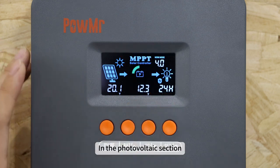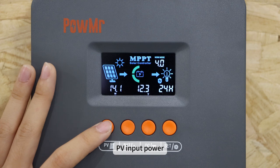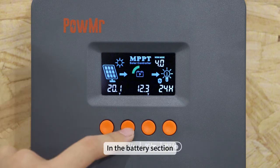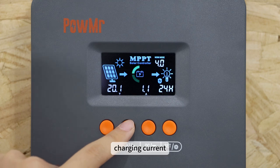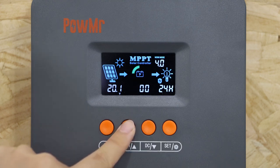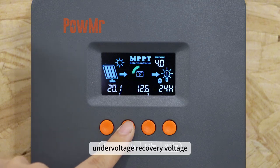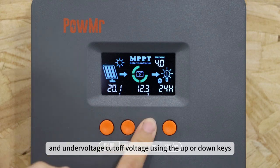modes. In the photovoltaic section, you can switch between PV input voltage, PV input power, and accumulated power generation by pressing the PV button. In the battery section, you can navigate through the charging voltage, charging current, device temperature, calibration voltage, parallel communication code, battery type, boost charging voltage, float charging voltage, under voltage recovery voltage, and under voltage cutoff voltage using the up or down keys.